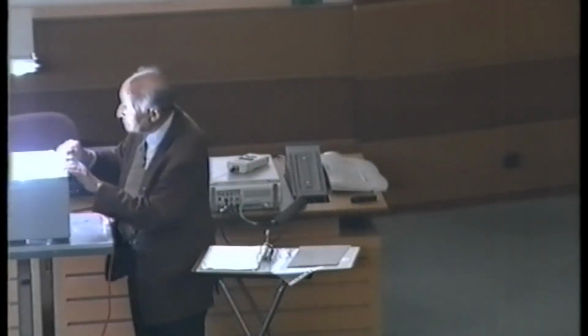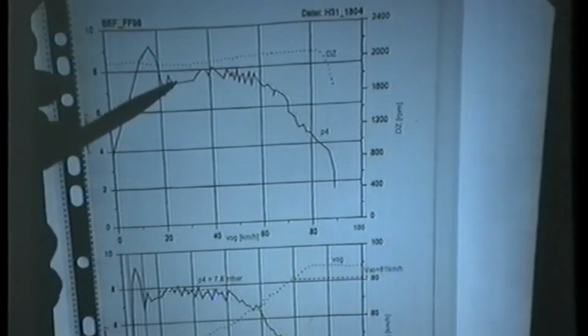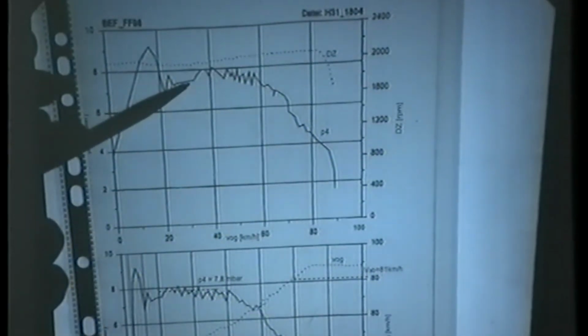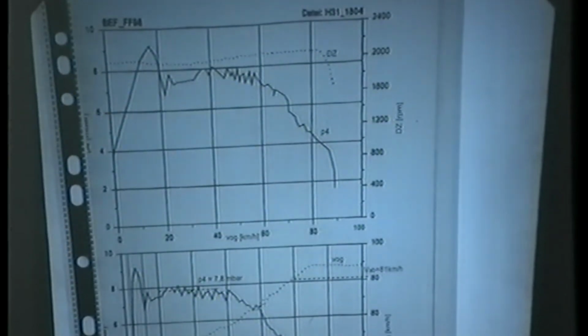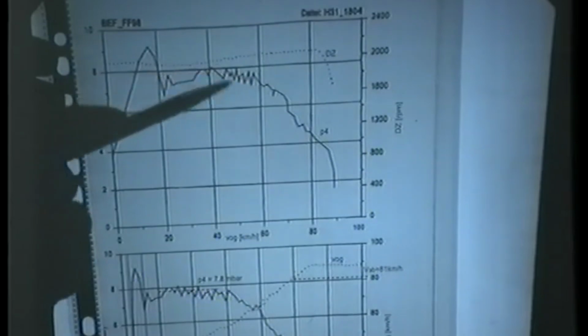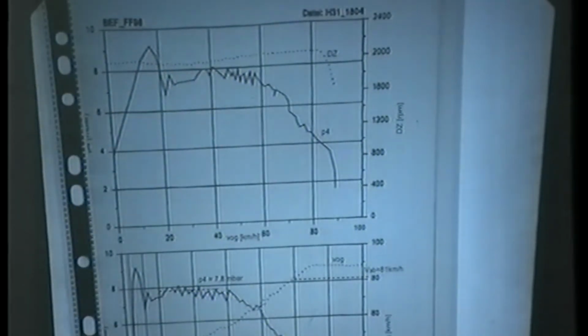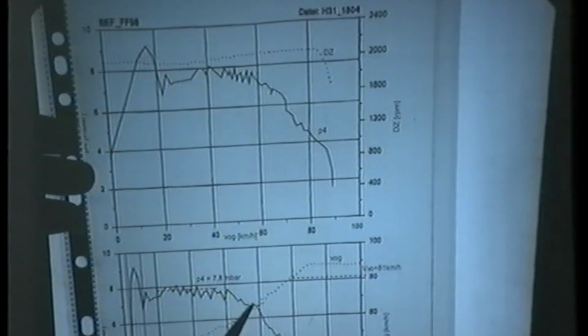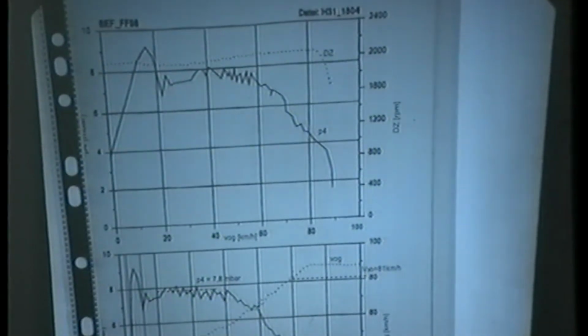But when you go forward with the speed, these are the result of some waves. There we have a small leakage, and you see this is the response from waves. But then the faster we go, the more by aerodynamic lift we come out of the water, and we have leakages. Unfortunately, we lose pressure. So to optimize how we seal the catamarans, we have only a small keel on the end. We try to keep the pressure as long as possible with the intention to reduce the wetted area.